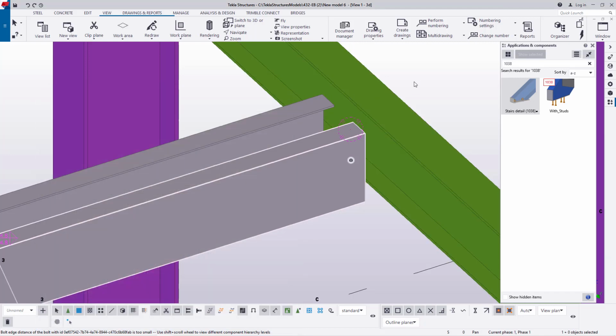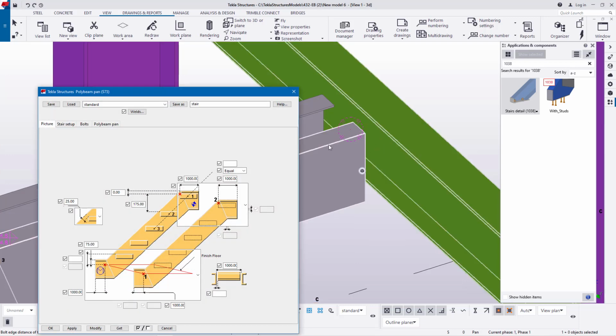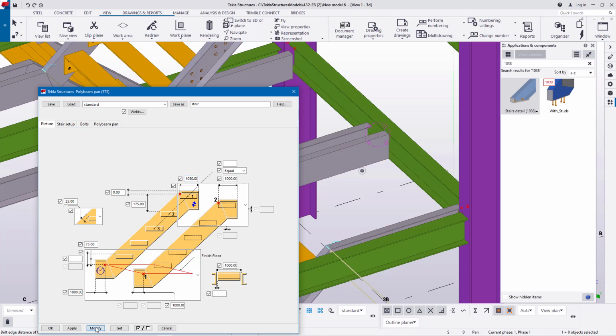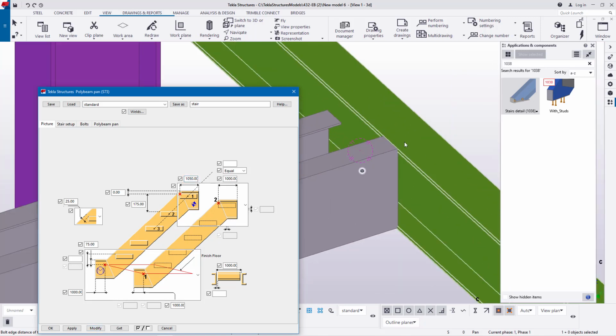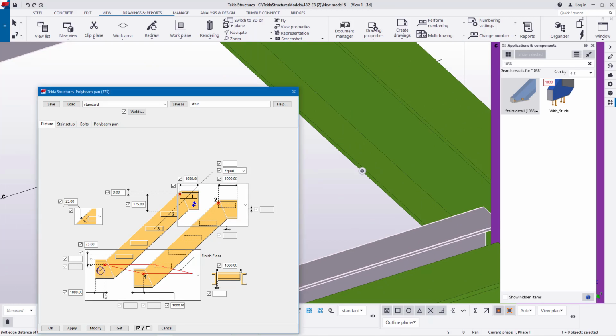Even though it's still the same, we need to adjust this to make it move slightly to the landing beam. Now I'll double click on it, then I'll come to the top here. I'll adjust this, I'll add around 50 there, and just move it right close, and this one also should be 50. Bottom end here should be 50.